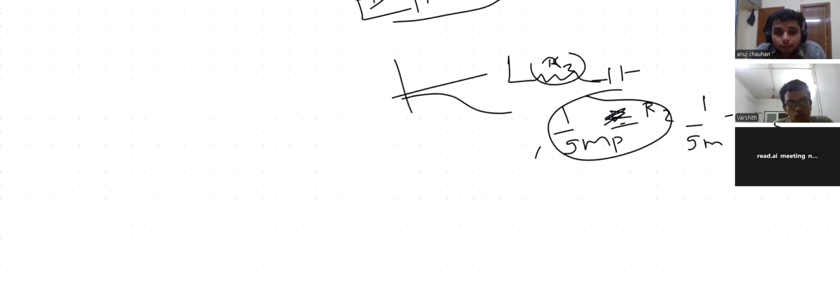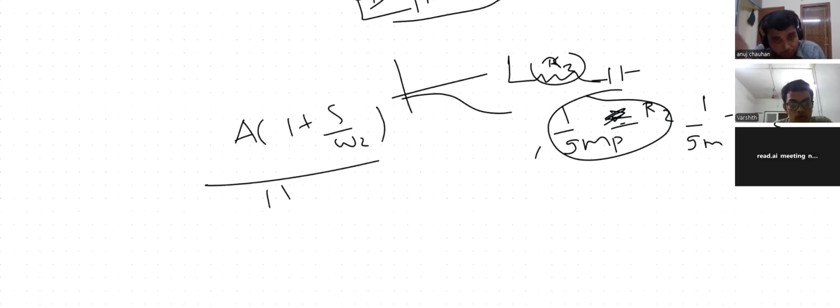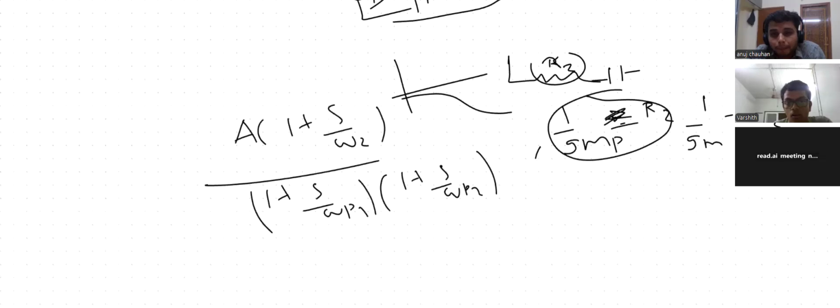A into 1 plus s by omega Z over 1 plus s by omega P1 times 1 plus s by omega P2. Where omega Z would be 1 by Cc into 1 by gm minus RZ, sir. If RZ is greater than 1 upon gm, then what? RZ minus 1 by gm, sir.